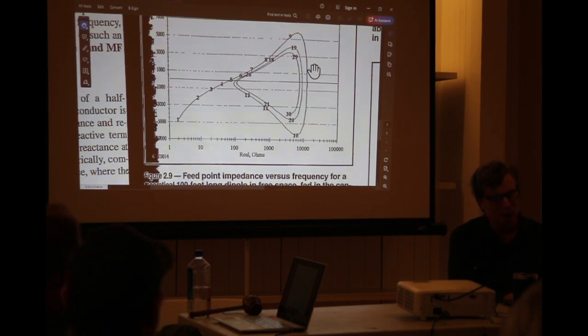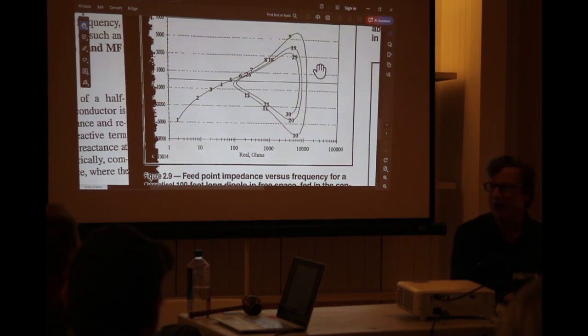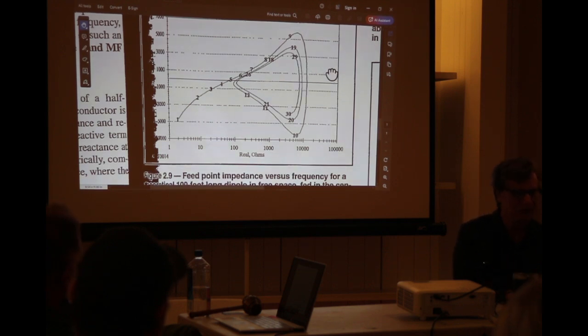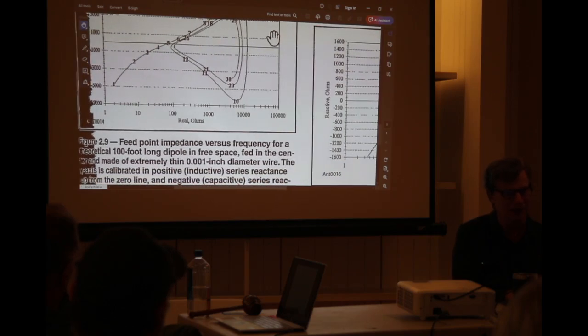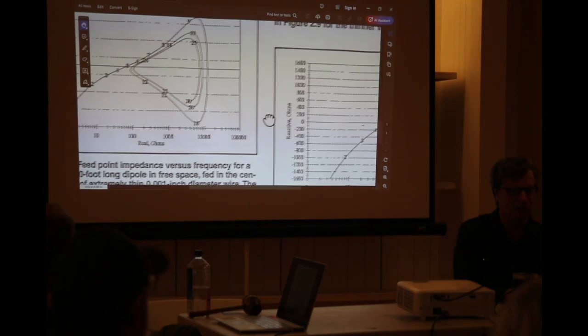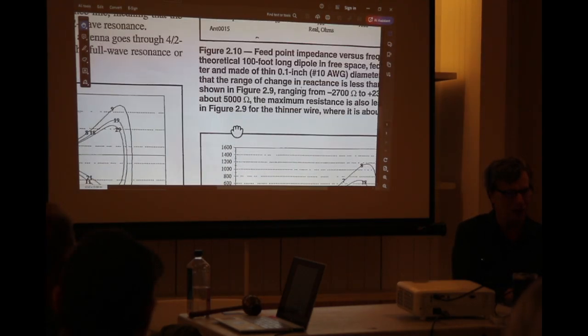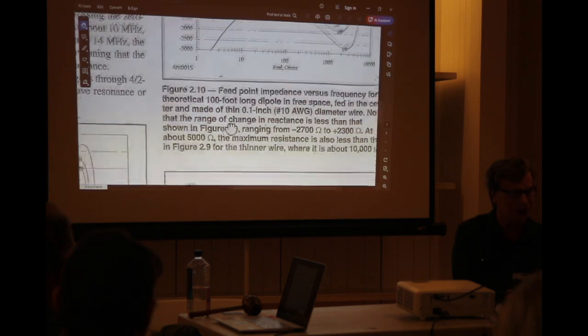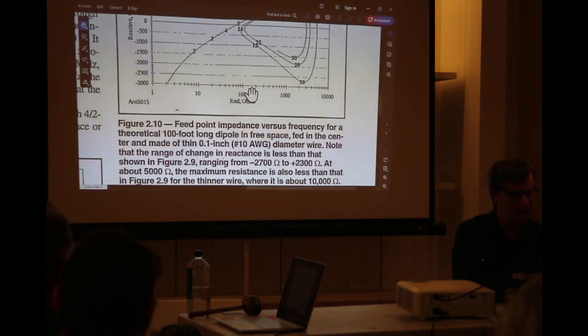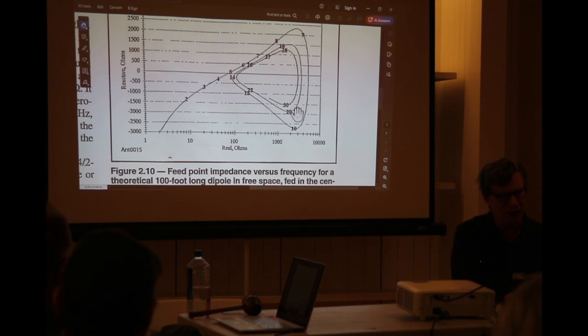But be aware that if you're building one of these antennas and you say, well, gee, I've got all these nice commercial, commercially available end-fed half-wave antennas, this thing is awfully touchy. Well, all the press doesn't tell you anything about what's happening over here. And we'll do some demonstration of a VNA, not on this particular antenna, but just some general rules for using a VNA. Now this chart's modified a little bit for actual, rather than extremely thin wires, using moderately thin wires, 0.1 inch. And so we don't have quite the extreme excursions here.